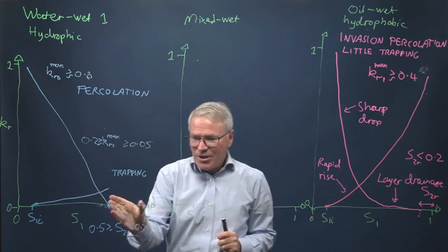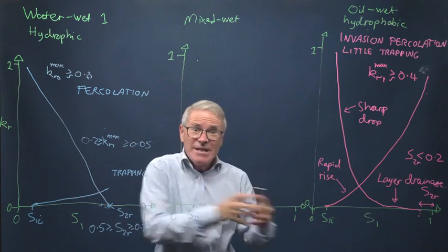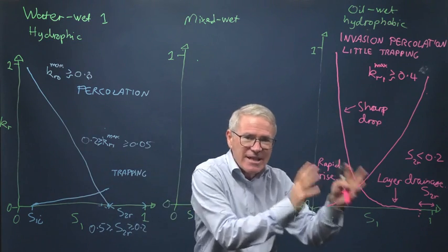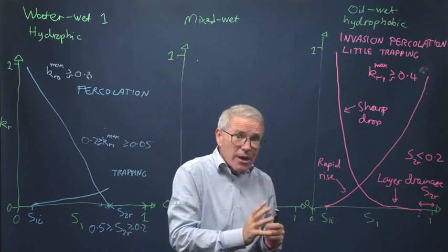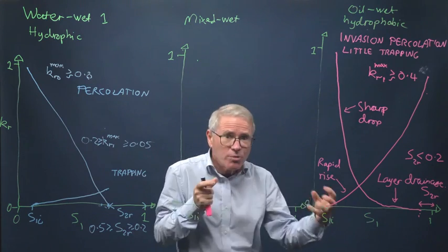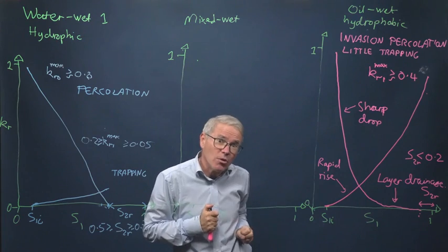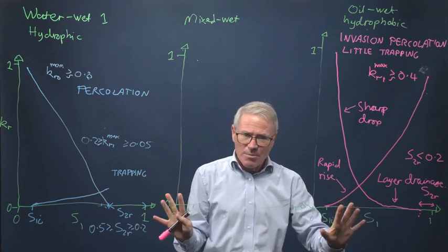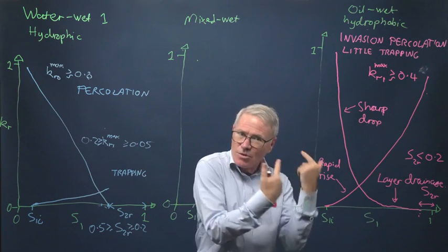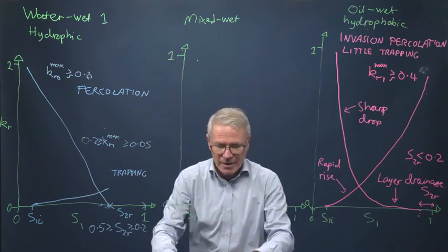In this case you get trapping, but in terms of recovery it actually isn't too bad because at least you get down to the residual saturation. This, in terms of recovery, certainly for oil recovery, is very bad, because you inject the water, it goes through all the large pores, it gets connected, it flows readily, and you retain a lot of the oil in the pore space. And that can be done rigorously, quantitatively with the mathematics. I'm just explaining it qualitatively, but it's entirely consistent with the physics of the displacement.